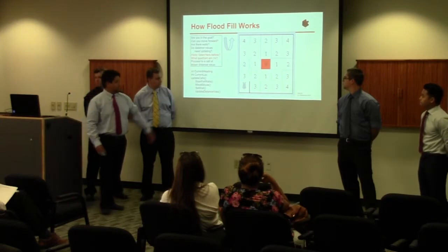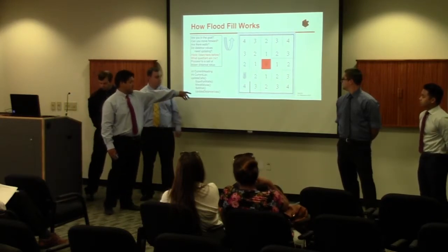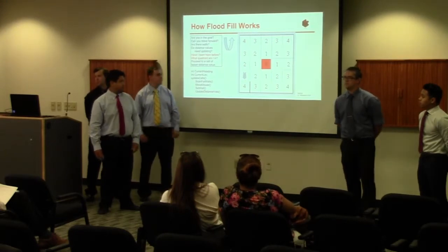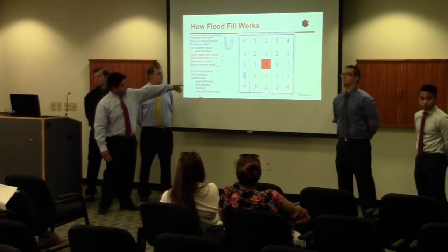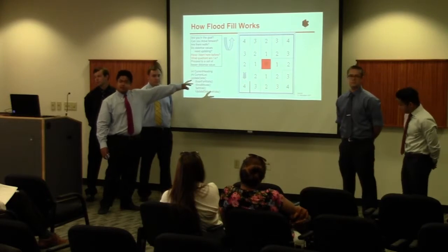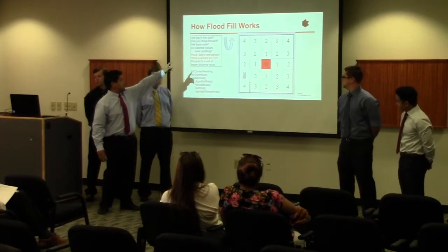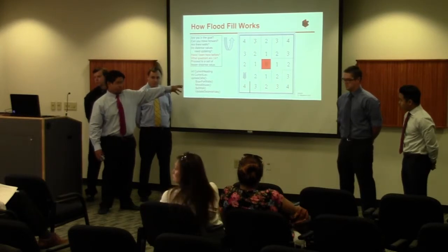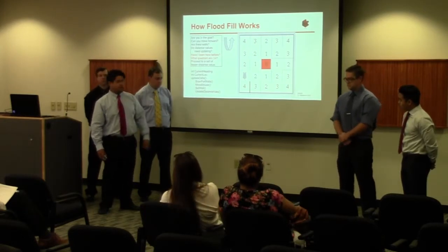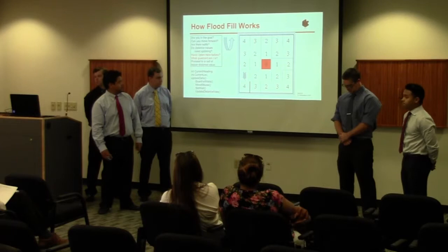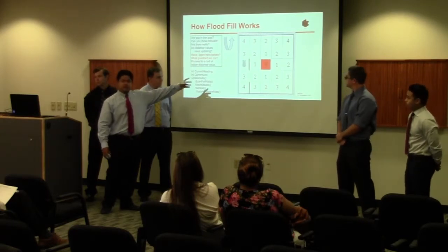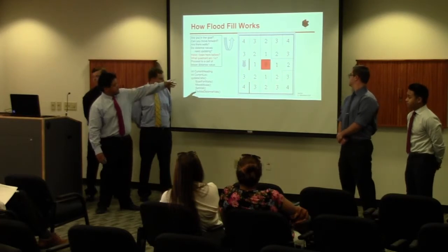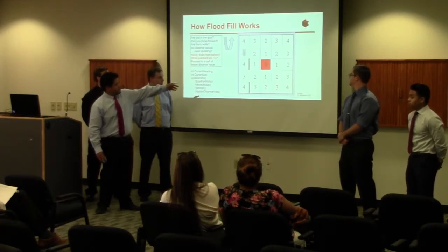So as we run the simulation of this mouse running through the maze, it's going to proceed to cell values that are lesser distance values. At this position, it has two cells that are equal value, so that's why the quadrant question comes into play. It'll come up to the decision to make an upward turn instead of a rightward turn. Once it enters that cell, it'll discover that wall using the sensor reading, and then proceed to here.